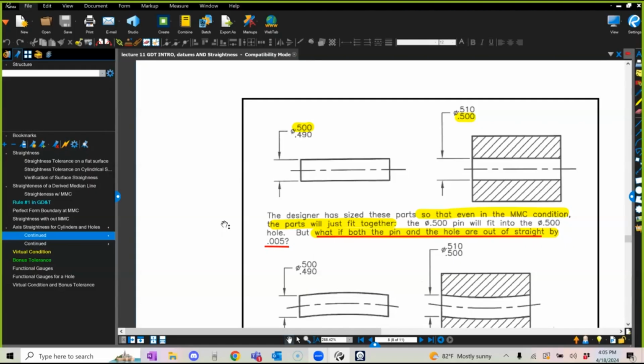So if I want to account for the imperfection and the size tolerance, I need to make my hole smallest, MMC, the worst case condition. And I also need to take away that geometric imperfection, because the geometric imperfection makes my hole become smaller. Does that make sense? So if I put all this together,